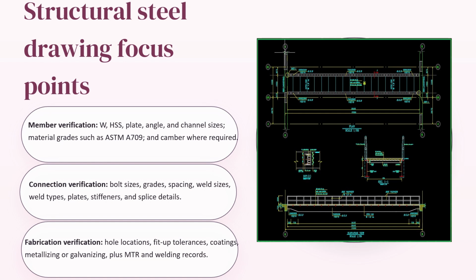Structural members you can physically see after construction unless enclosed, such as beams, columns, and connection plates. The skeleton or frame of the structure is the structural steel shop drawing. It is used for canopy framing, pile foundation steel, girders, frames, sign structures. The typical components are wide flange beams and columns, plates, angles, channels, HSS members, gusset plates, stiffeners, base plates, anchor rods, bolts and welds. Examples include canopy framing, girder diaphragm, sign structures, steel frames, pile foundation structures, steel details.